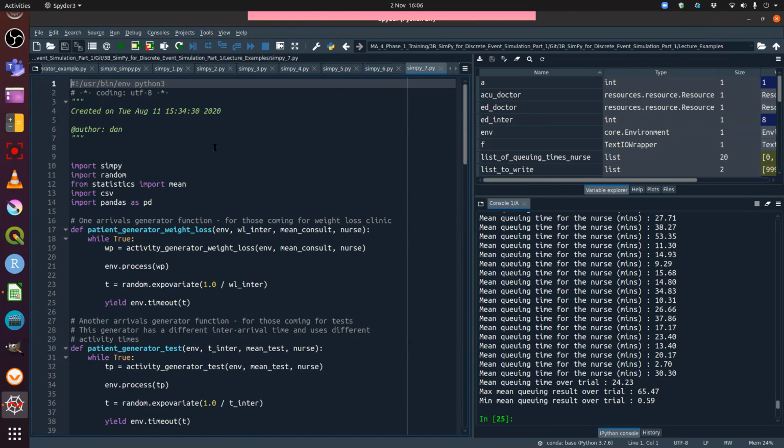Yeah, so in part that is showing you that you can. I would typically, for very large scale models, so for something like this that runs in half a second, it doesn't matter. But you could end up with a very big model that takes days to run. And if you've got something like that, it's very good practice to be writing out to file, because if anything happens to your simulation halfway through, or somebody accidentally crashes or turns off the computer, particularly if you're using cloud computing or something like that, what you don't want to happen is everything to be lost. And obviously if you're only storing it internally in the program, in the memory, that'll all be wiped.